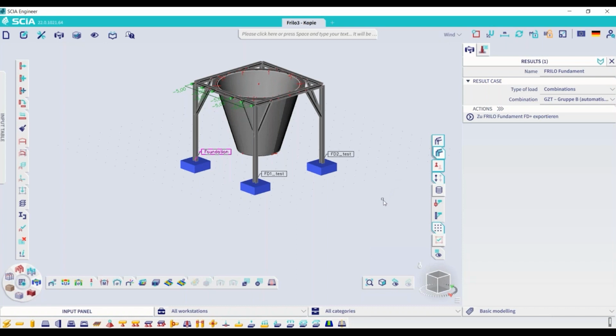always be aware of which type of calculation is done. So is it a linear one or a non-linear one? And according to that calculation, define which loads need to be transferred. So are we talking about characteristic loads? That is absolutely sufficient if we have a linear calculation, to hand over characteristic loads.